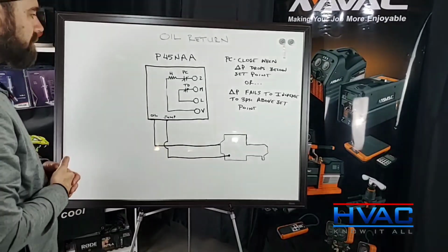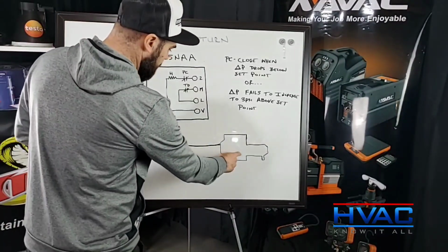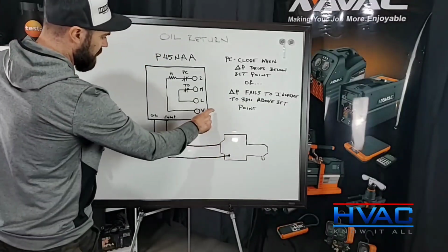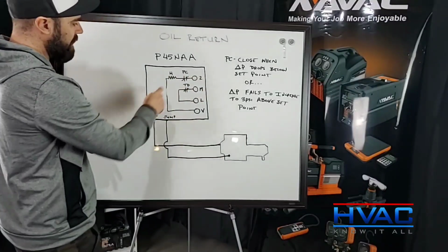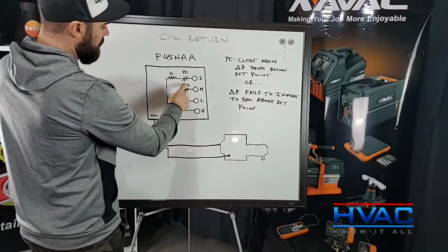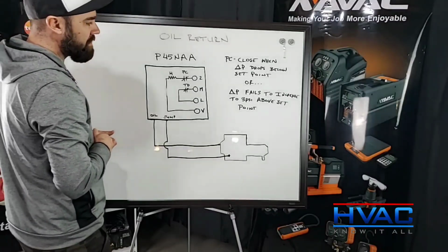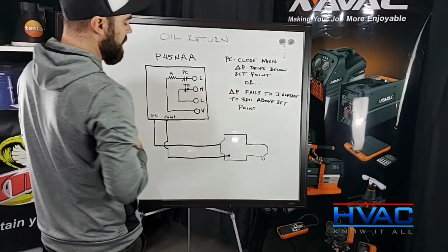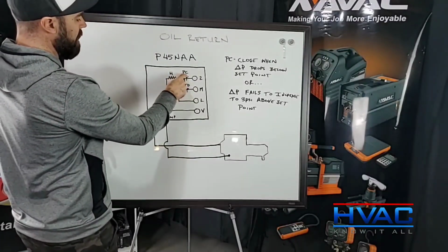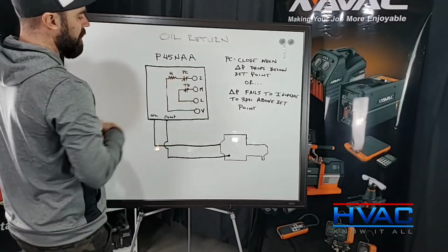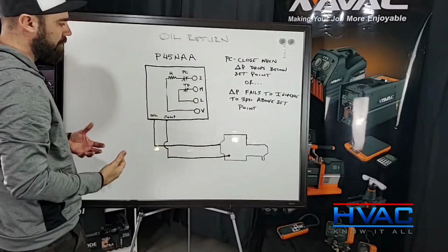All right? If the compressor's already running, let's say we go through this. Let's say the compressor starts. We send power through here. The heater starts up. Our time delay is activated. Okay? But let's say we get 3 psi above set point. This will open. This will now open up. This is a pressure activated contact. This will open. The heater will be taken out of the circuit.